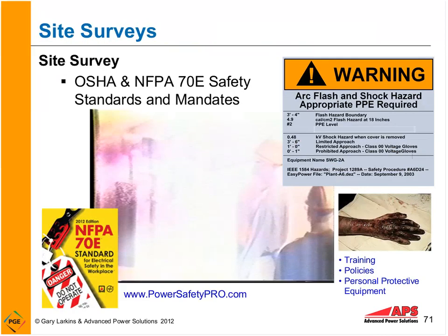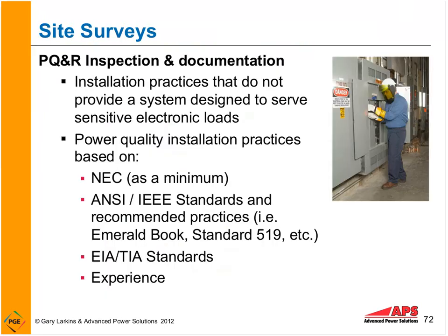So when you're doing a site survey, always pay attention to safety issues, arc flash and shock hazards. So when you're going to hook up equipment, go out and do inspections, please pay attention to the safety issues so that you don't hurt yourself. Document, go out, take measurements, inspect the systems, document what you observe, what you measure, compare that against the National Electrical Code and power quality installation practices, such as described in the IEEE Emerald Book or the IEEE Standard 519.